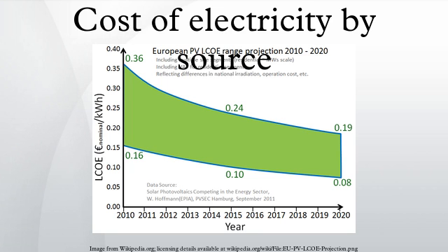In particular, assumption of capacity factor has significant impact on the calculation of LCOE. For example, solar PV may have a capacity factor as low as 10% depending on location. Thus, a key requirement for the analysis is a clear statement of the applicability of the analysis based on justified assumptions.